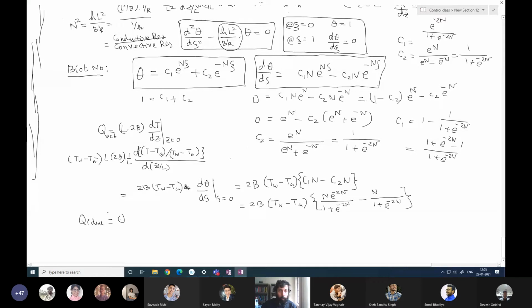or Q max equals to the width is, what was that width, right? Width times L, that is again twice up and down surface, and the entire surface is at a temperature of TA, there's a TW minus TA. So this is the convective heat flux. This is the area through which convective heat flux is happening. All the side and tip areas have been neglected.